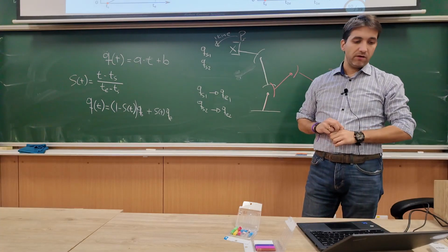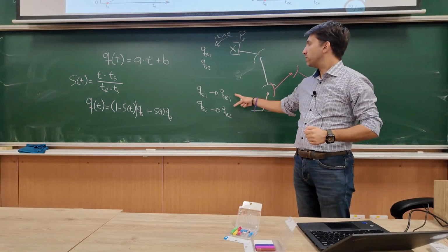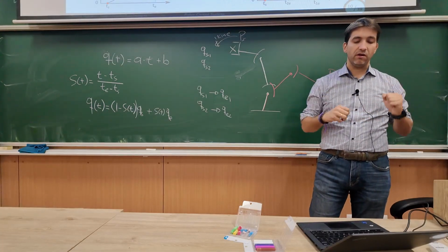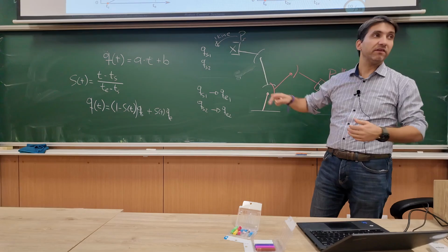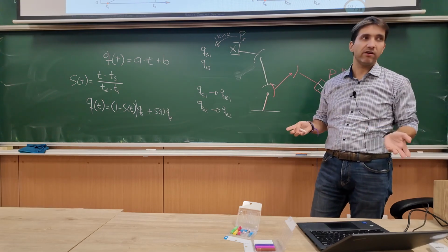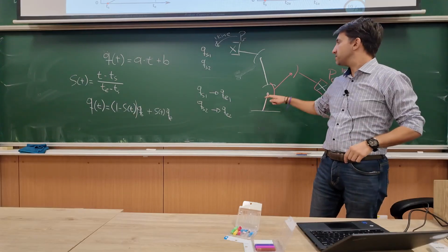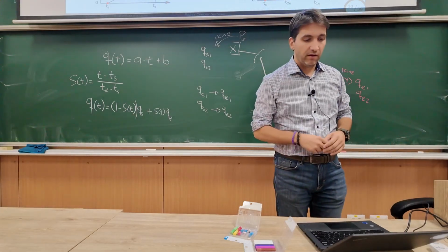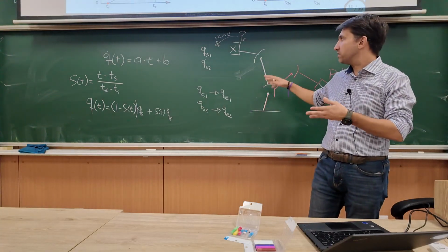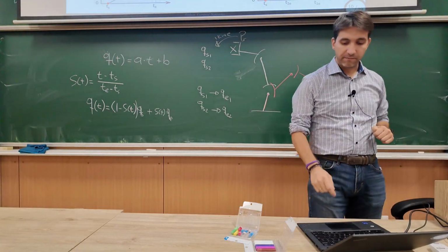So then, yes, here we present the method to interpolate from one pose to the other. We have a smooth transition, but what will happen at the end effector is definitely not going to be in line, unless these are prismatic joints. But in the general case where we have revolute and prismatic and whatnot, it's not going to be a line.